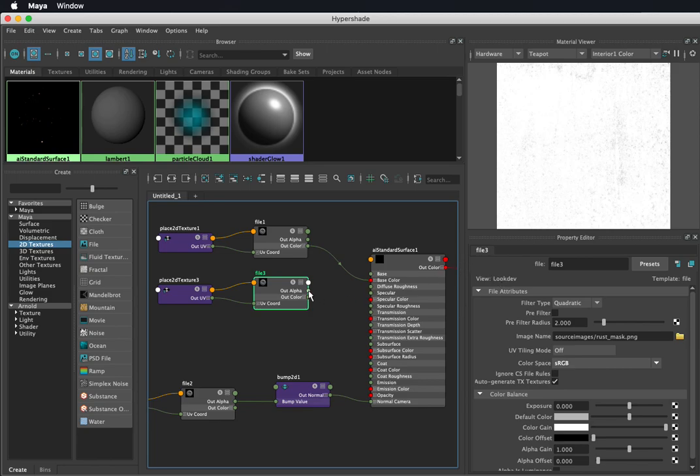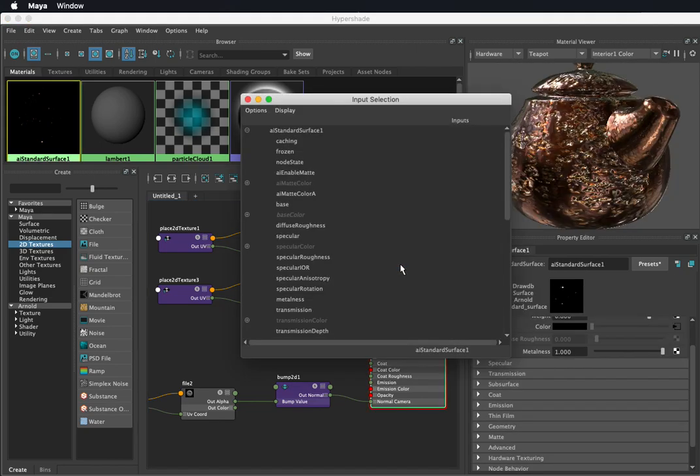And what I'm going to do is take this alpha value here, so the alpha is the transparency values, and I'm going to put that into Metalness. But you'll notice that there is no Metalness listed down here. This dot at the top is for the most common things that people use. This big dot up here is for all the other values. So we click on that one, click other, and you'll see that one of these items listed here will be Metalness, right here.